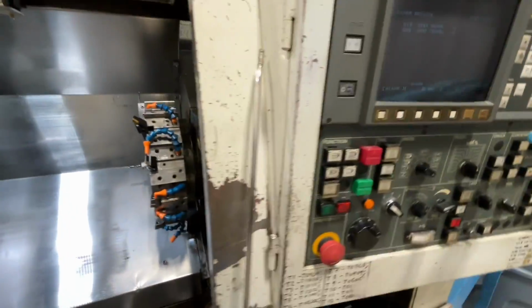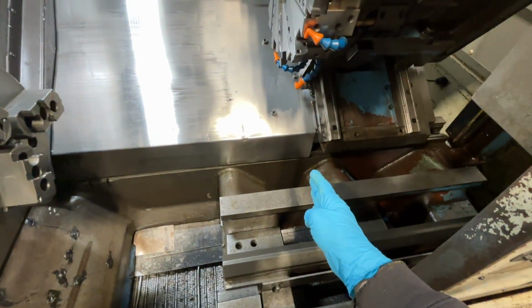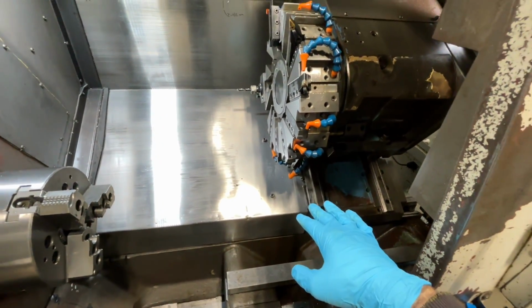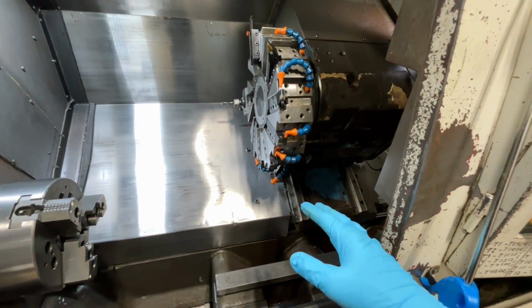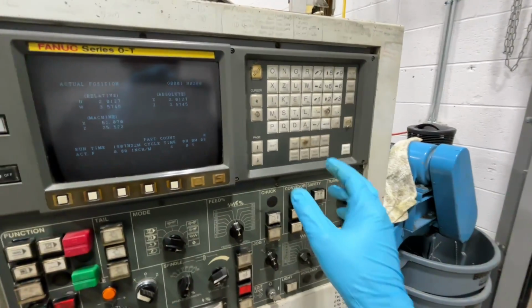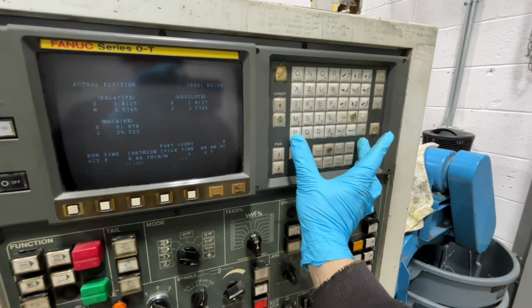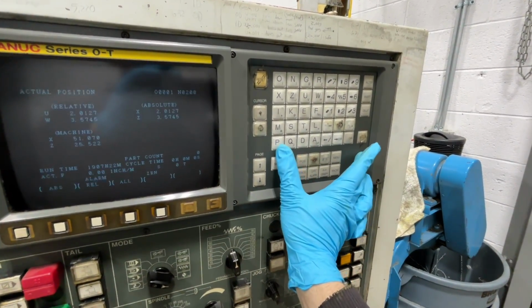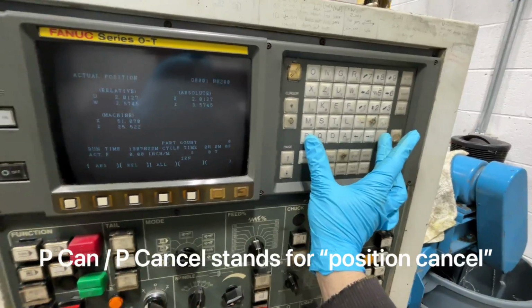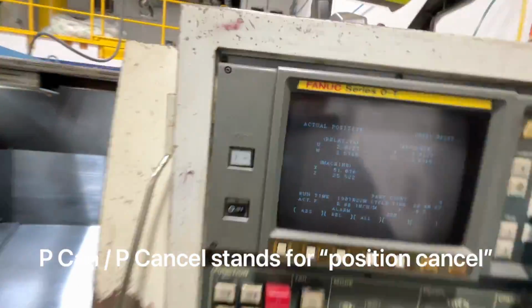So the problem with that is the machine still thinks that home is back where we were before. So we have to do this technique called P-cancel. It'd be better if you read up on it than me explaining it. But what we're gonna do is when the machine is off, we're gonna hold P and cancel while we boot up the machine.